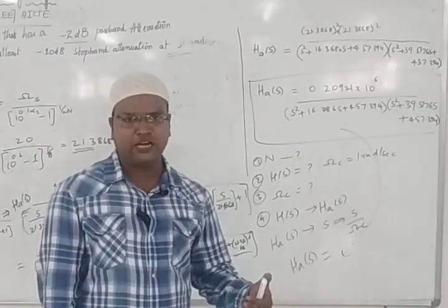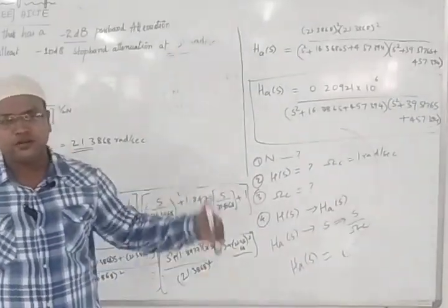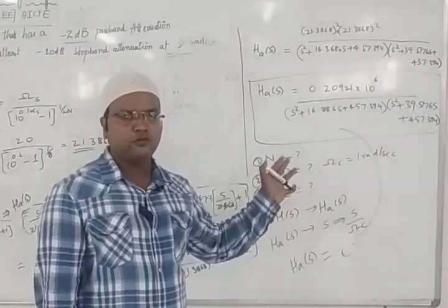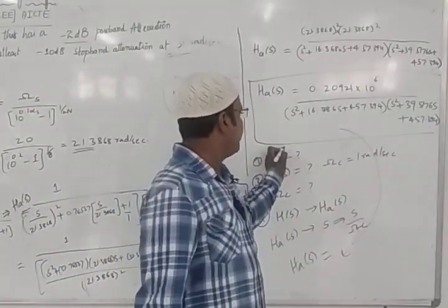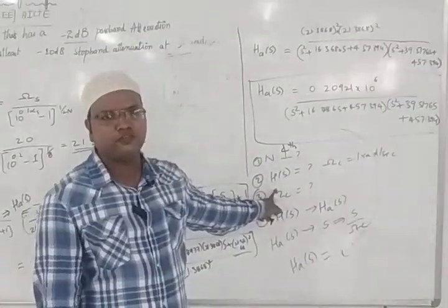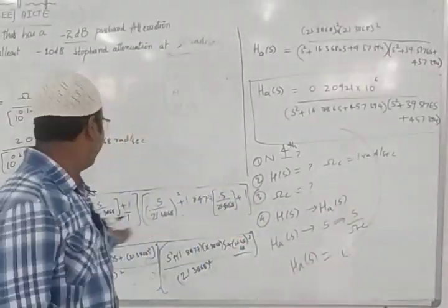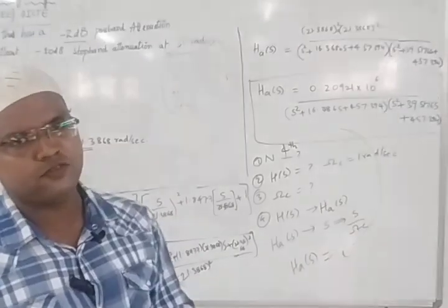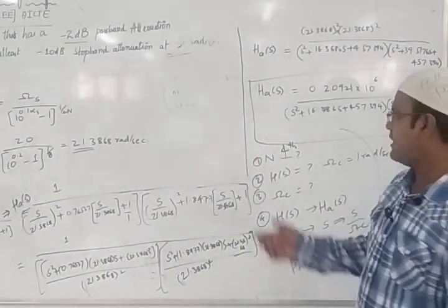So we took these two factors, we got N greater than whatever values we have, that is 3.37. The N needs to be more than that. So we took the value more than 3.37, that is nothing but 4. So we got fourth order. What we got for N value? We got fourth. So what does this fourth mean? We need to assume what is H of S, the denominator of H of S. For the fourth order, what is the value we have? S square plus 0.76537S plus 1, and S square plus 1.868477S plus 1. We got that. So that is nothing but the fourth order.